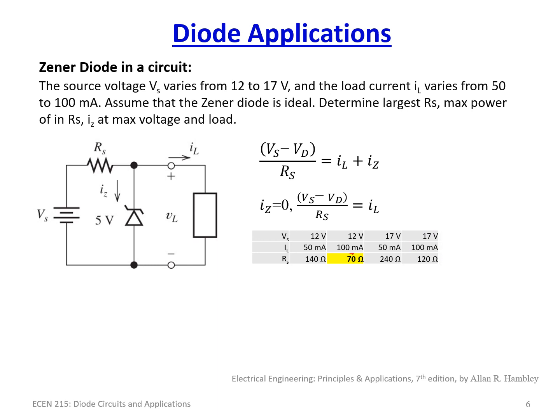Now, why did we choose 70 ohms? Because you had to make all of these conditions work. So we had to be able to support the lowest voltage at the maximum current. So with IZ equal to 0, which means all of the power is going to the load, and there's nothing else going through the Zener diode. That means we're dropping everything across Rs. That means this is our lowest point right here, lowest point of resistance for this.